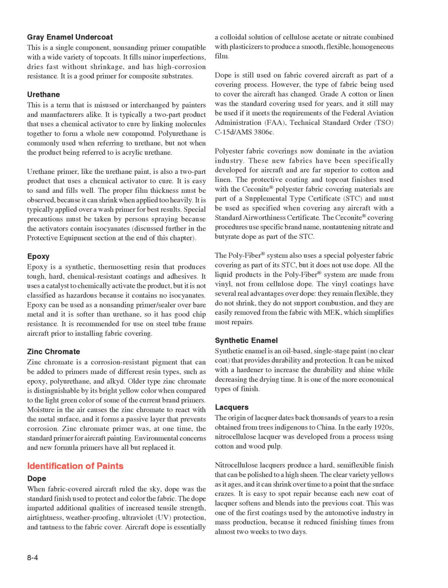It fills well. The proper film thickness must be observed, because it can shrink when applied too heavily. It is typically applied over a wash primer for best results. Special precautions must be taken by persons spraying because the activators contain isocyanates, discussed further in the protective equipment section at the end of this chapter.